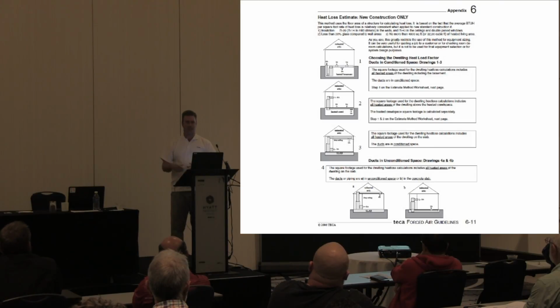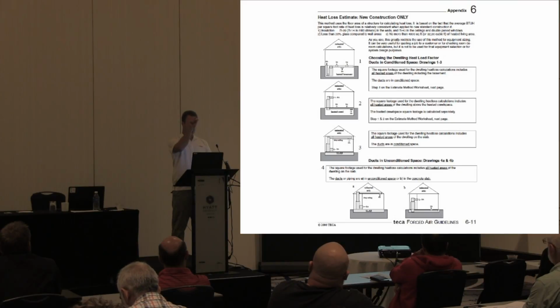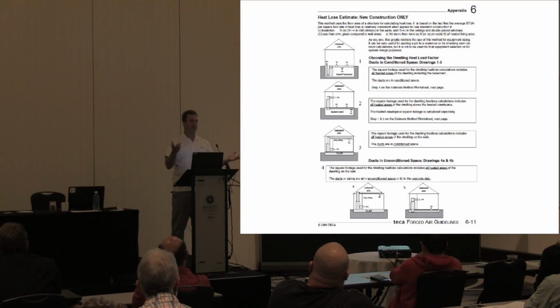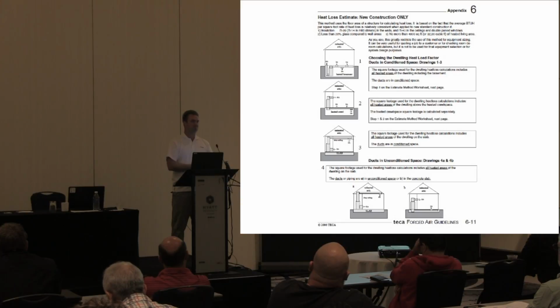If I can get it done quickly enough, I have one on my computer, but it's not on here, and I can show it to you. Basically it's quick line multiplication. You put your factor in, you put the square footage of each item in, and get a total at the bottom. Even with the limited experience you have doing heat losses, you'll have a rough calculation in probably 15 minutes to half an hour. It'll take you longer to pull the information off the plan.